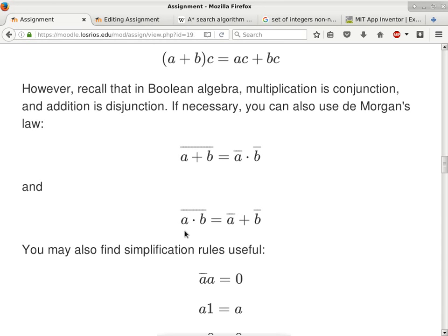Okay. Now these are all just claims. If you want to prove that De Morgan's law works, you can make your own truth table, go through each and every single one of these and prove that it works. And these are a whole lot easier because you only got two independent variables, which means you only got 4 rows, and it's pretty easy to finish. Yep. These are the exact same thing as A plus B in parentheses and a negation on the outside. Yep. But this is the more compact way to express it.